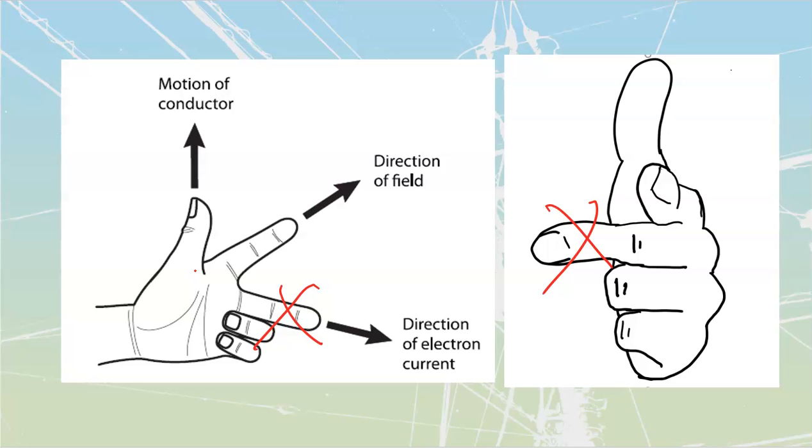That's straightforward enough. The second one over there is where they say, well, we're going to keep the same length of conductor, we're going to keep the same flux density, but now we want to speed up our movement through it so that we can produce 347 volts. And so then they go through the reworking of that one. Example number 3 talks about keeping it at that same value of speed that they just moved it up to, but now dropping the amount of flux, the amount of current going to those field poles, to drop the amount of voltage that we are going to have.